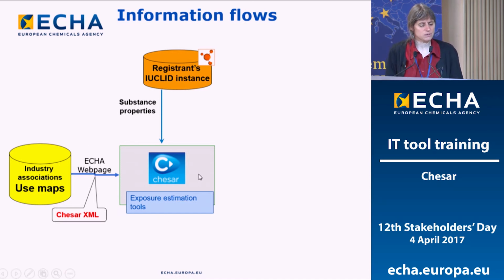It's the registrant's tool. In fact, it enables you to import directly the information on the substance properties from the registrant's IUCLID instance. So all the key information which is useful for the chemical safety assessment and which is reported in the IUCLID technical dossier is imported directly into Chesar. And then there is also a possibility to import use maps, if they are provided by the sectors in a Chesar format, they can be imported directly, with one click, and all the information gets there into Chesar.